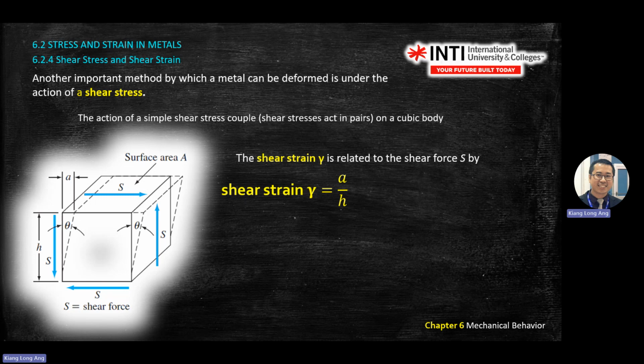It's hidden information. If the question gives you an angle, like it tells you the jelly block or the metal deforms at a certain degree, it means like this. So it also means tangent. So it gives you another relationship with G, the shear modulus in the table just now. Hooke's law for shear: shear stress equals the coefficient times the shear strain. Just now, stress equals capital E times strain. Another one is shear stress equals G gamma. This is an important equation for this chapter, chapter 6, very important.